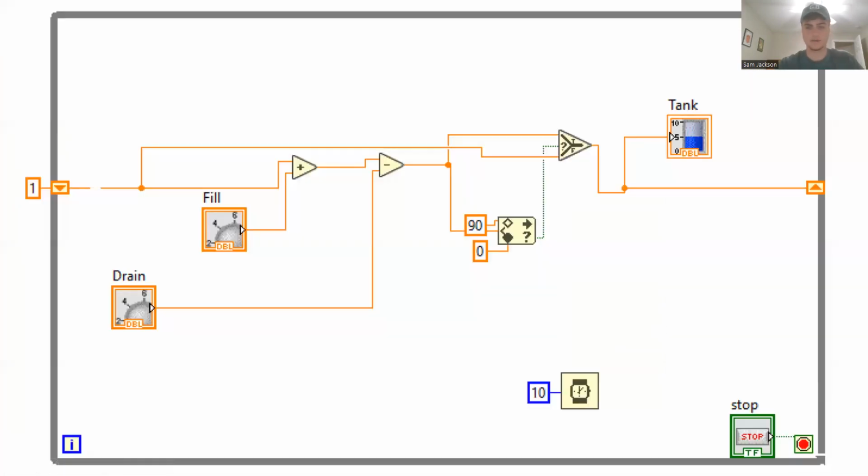So now I just want to explain kind of what happened in that video. It was important to mention at the beginning, on the first process that we did, the first drain and fill, the max was set to 95 and the min was set to 0 and the wait was set to 10. And from there, we can see that it directly affected the rate at which it filled. Because the wait was only set to 10, it was set to do the drain and fill process one time in 10 milliseconds actually. And so it filled incredibly fast and drained incredibly fast.